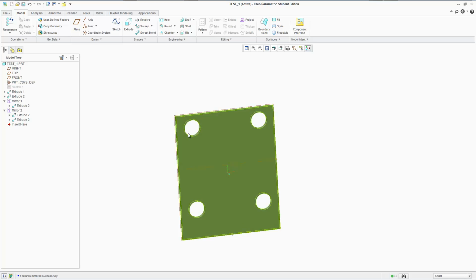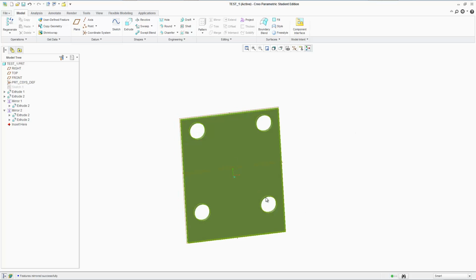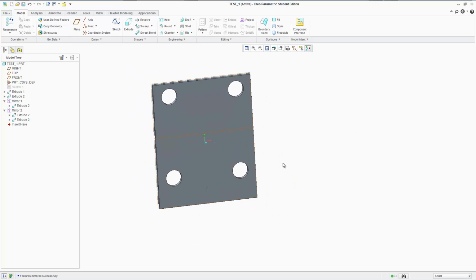If you're making holes in a plate that you want to use as a mounting plate for some equipment, it's a nice feature if it's symmetrical. You don't have to use the pattern command for that, because if the dimensions are the same from the edges on all the corners, you can just use this and it's nice and quick. That's that for now.